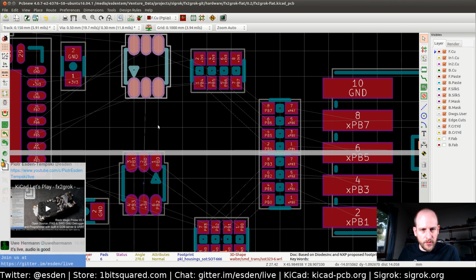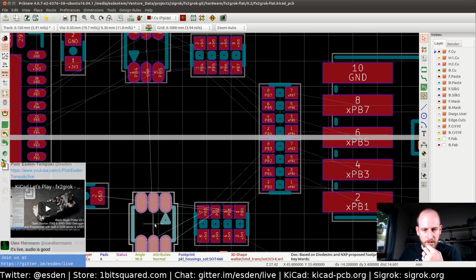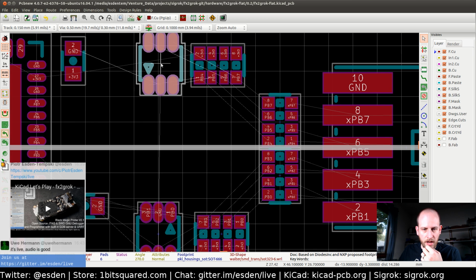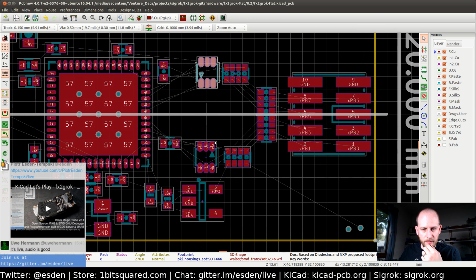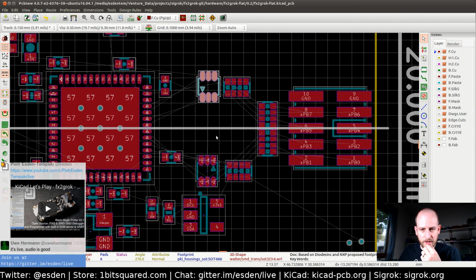Then how to do this? We probably will do a similar thing where we basically tap off the straight traces that go to the microcontroller and basically tap into the lines using vias from the backside. I think that might do the job.